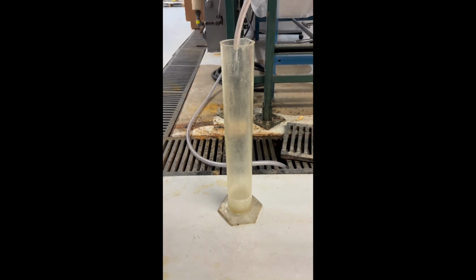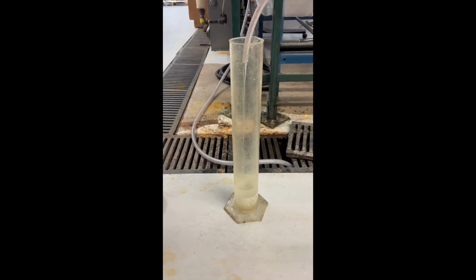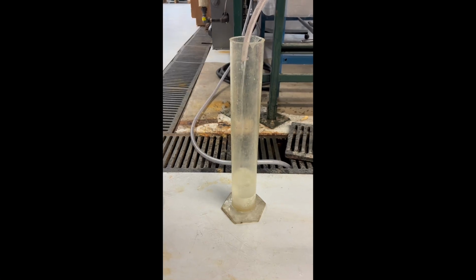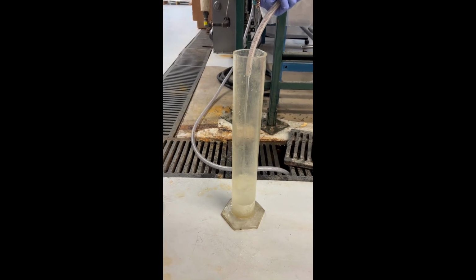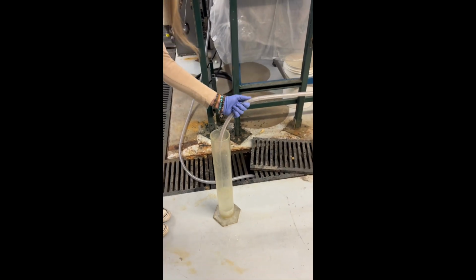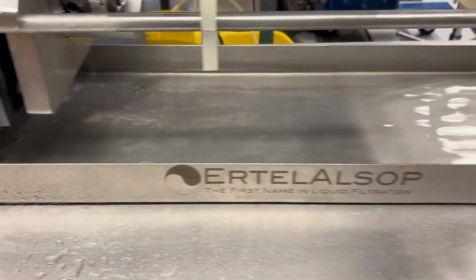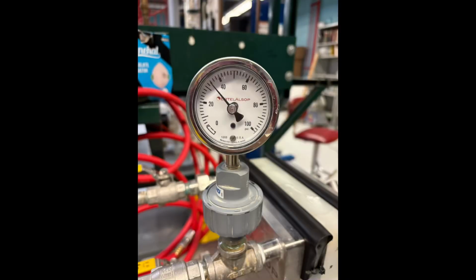Once beginning the trial, filtrate should be monitored at every 250 milliliter interval. Once the filtrate reaches each interval, note the time in seconds. Continue to do this until the slurry is completely gone. Some of the sand may remain at the bottom of the bucket, and much of the liquid will leak into the drip plate. During the experiment, monitor the pressure gauge attached to the filter press. Record the pressure before the trial and after the trial. This will be the pressure drop.